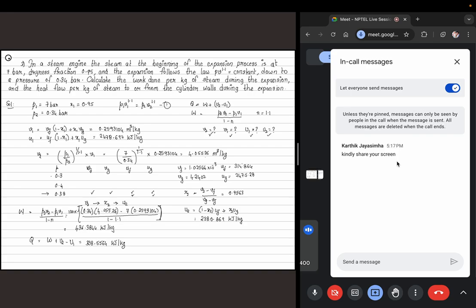The only thing that we have done extra here from the last problem is that now we have to do two interpolations. The first interpolation is because you need to determine the properties at a pressure that is not provided directly in the steam table. Second, up until now we have been just looking up the saturated pressure values. Now we calculated the vapor fraction indirectly based on the V value that we obtained using the polytropic process.